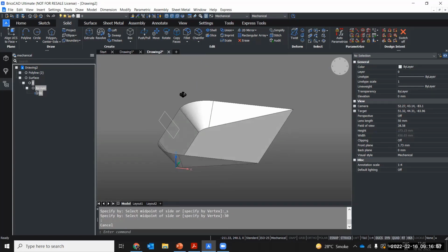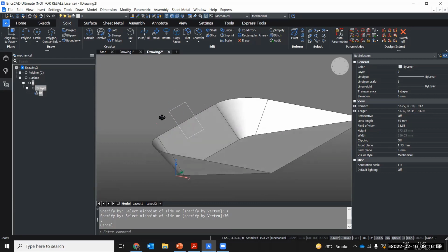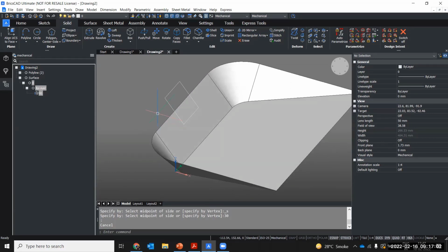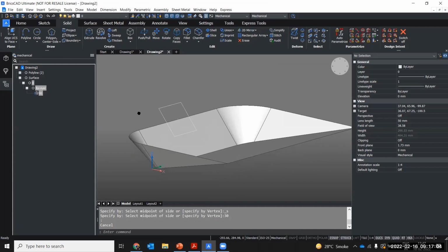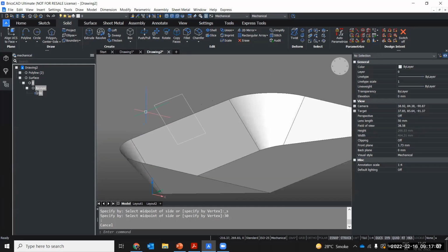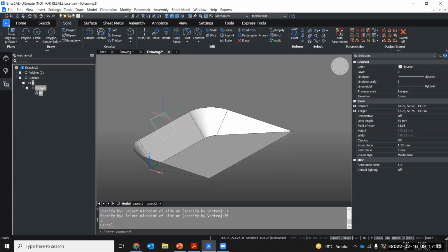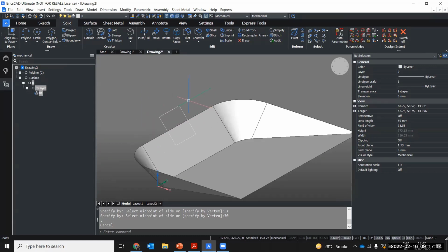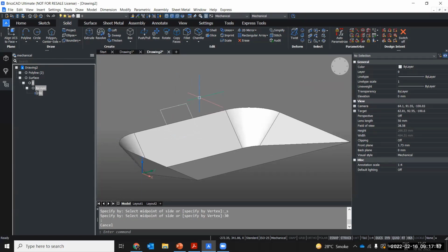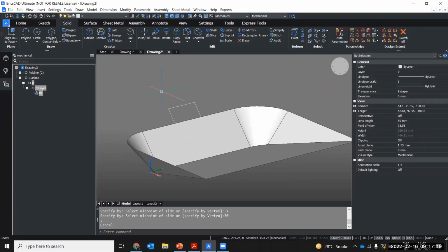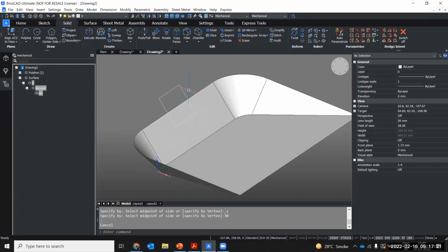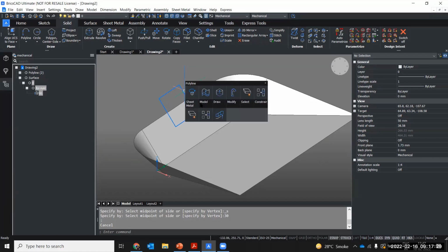Don't draw exactly on that particular surface. So this is the help of dynamic UCS. Whereas specifically in the CAD softwares that are available in the market, Inventor, SolidWorks, you need to create a lot of planes, and this is where BricsCAD Mechanical is quite powerful in terms of the design freedom that you have inside the software. So coming back to the exercise, now you have this particular profile that is there with you. Simply hover over this profile and again execute the same command, surface extrude.